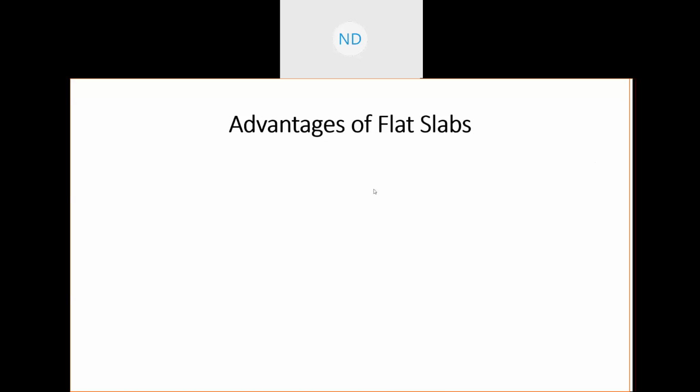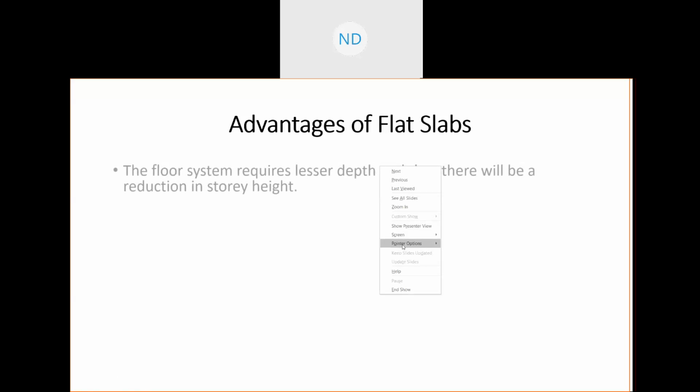So let's talk about the advantages of flat slabs. The first point, if we see: in flat slab floor systems, we require lesser depth, and thus there will be a better reduction in the story height.